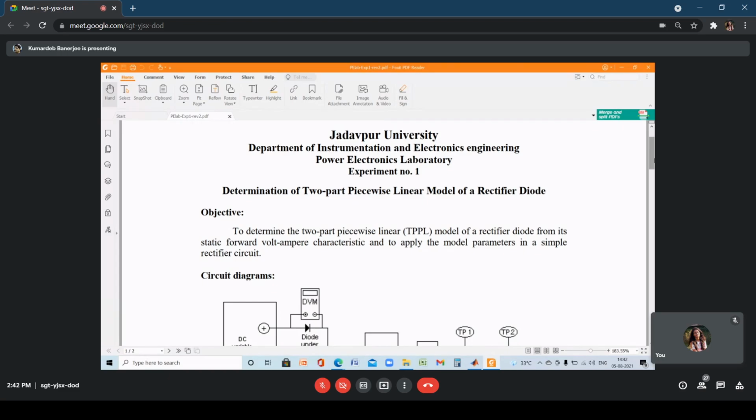For example, a full wave rectifier is a circuit, and we need to analyze the circuit to find out the essential components of current and voltage across and through each and every component in the circuit. If I have a nonlinear element, nonlinear in the sense that the VI characteristic is not a linear equation, then it becomes difficult to find the current, because it does not have a very simple expression. It's something like I0 into e to the power of qV, minus 1, where q is a constant. I0 is the reverse saturation current.